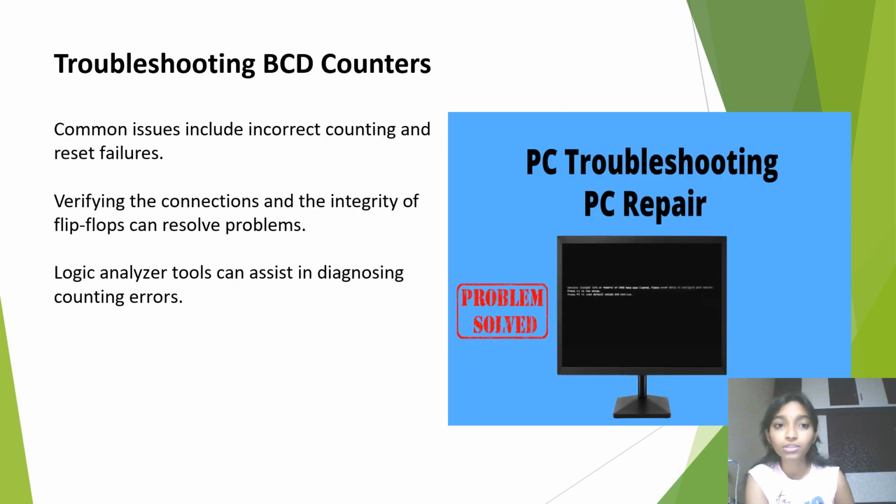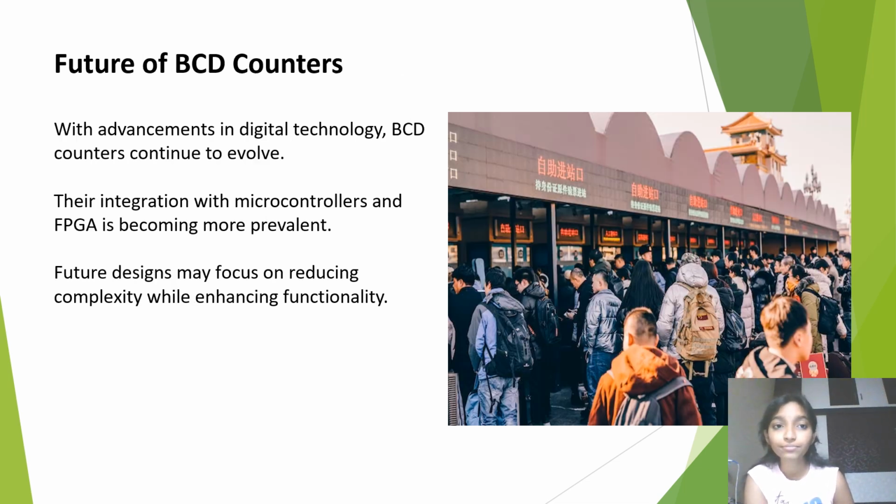Troubleshooting BCD counters. Common issues include incorrect counting and reset failures. Verifying the connections and the integrity of flip-flops can resolve problems. Logic analyzer tools can assist in diagnosing counting errors.